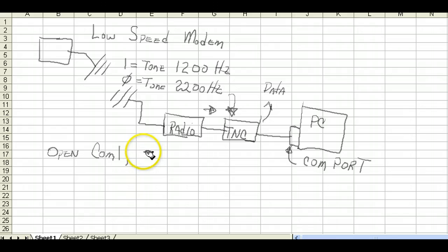Typically the data rate at which we transfer data from here to here is 9600, but it could be many others. So we put 9600, and then we tell it how many bits it sends, how many stop bits we send, and how much parity. From language to language these things will vary, so when you pick the language in the computer, you look these things up, and there are some other parameters we can send in here.